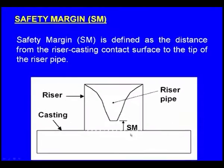If the safety margin is more and more, that extra length of the riser is not involved in feeding the casting, which is a wastage only. So, the safety margin should be minimum, it should not be too much. On the other hand, it should not be 0, because 0 means it will be just touching, and it should not be negative.